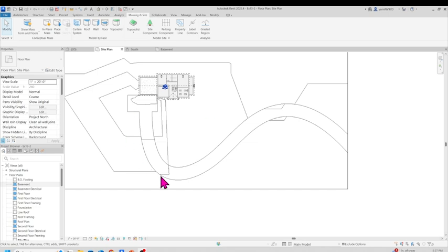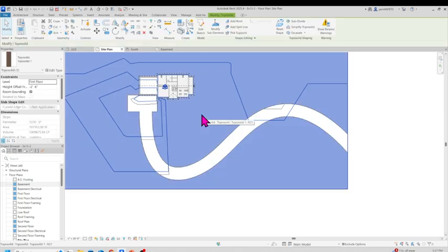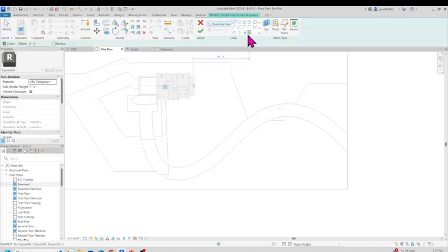Okay, let's put a sidewalk in here. We can put a sidewalk on this side, coming out of the house. We can connect these two together. One of the things we can do is, again, highlight this, subdivide, and then I'm going to use a pick line and make it 5 feet. A normal sidewalk is about 5 feet wide anyway. So we're going to come in here and click this line. It does it in a segment, remember, right there. Okay, that's fine. Click whatever is available to you.